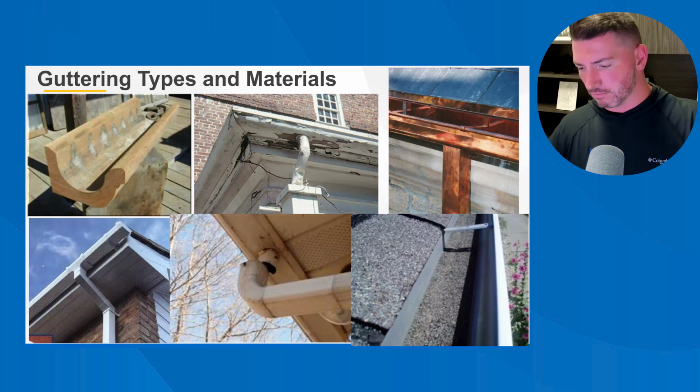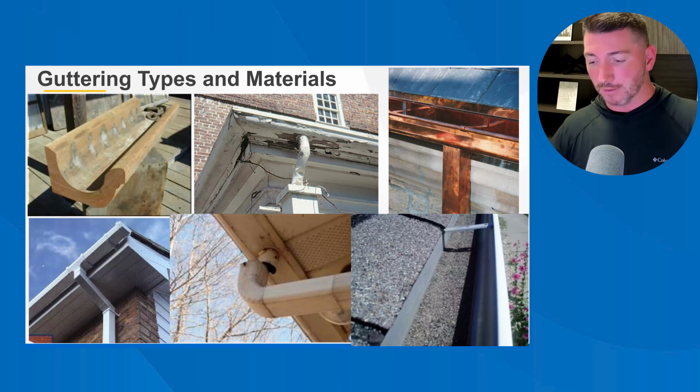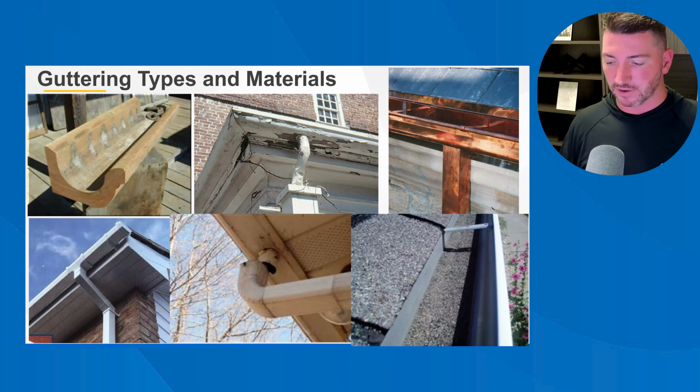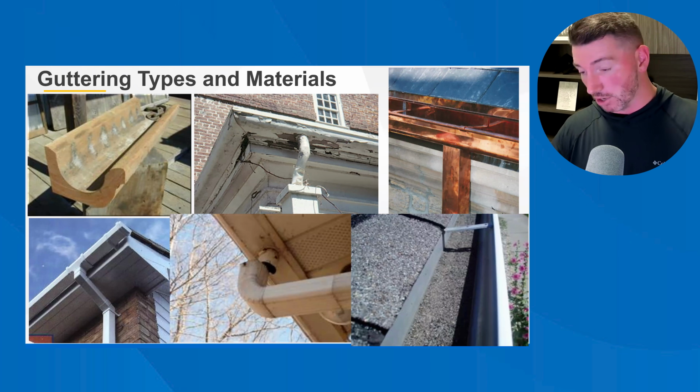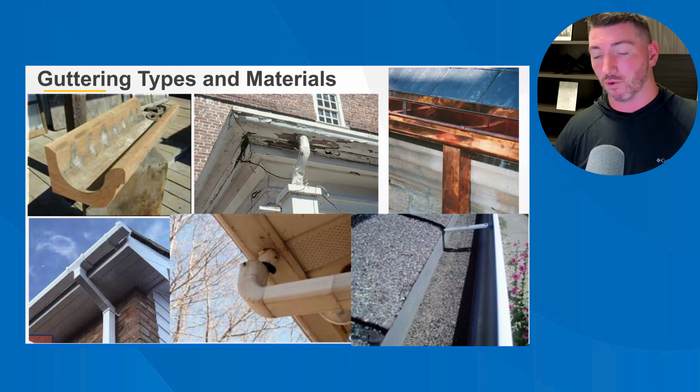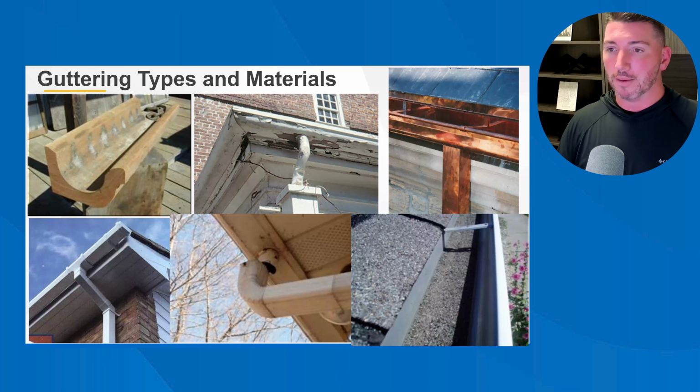So that aluminum guttering, it does come in 10-foot lengths. If you walk into Lowe's, you can get aluminum gutters at 10-foot lengths and they'll have seams. But it's usually on site with a roll of sheet aluminum, and that leads to fewer joints. And then, at the corners, inside corners and outside corners, you're still going to have connections and you want to evaluate those areas. So if you walk up to a modern build, and I say modern, could be 20 years old, but more modern than a house that was built in the 60s with gutters from the 60s.